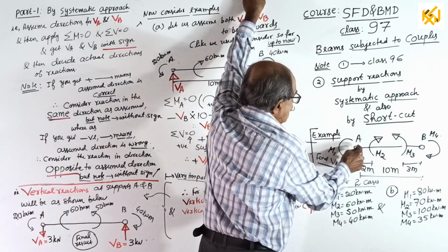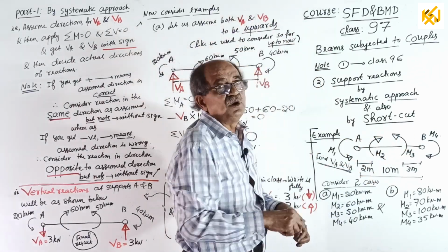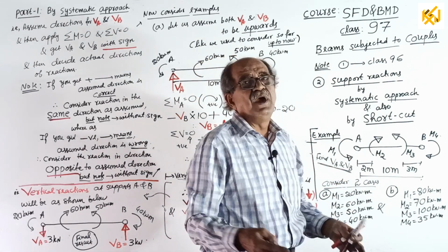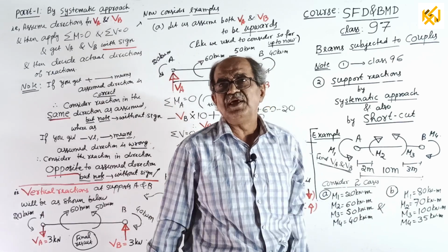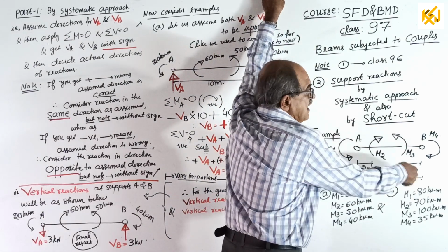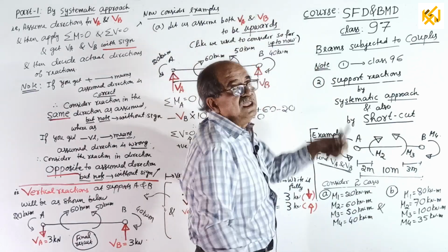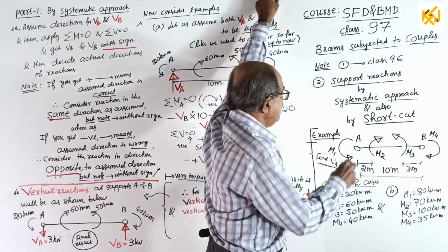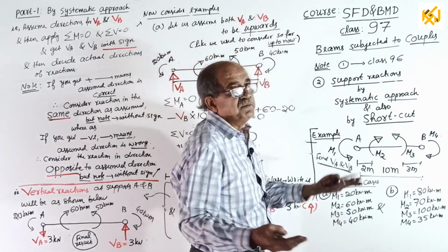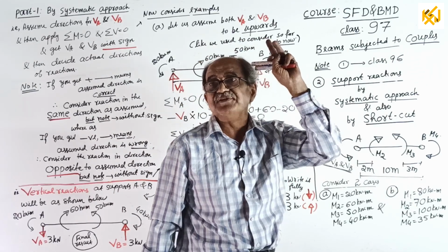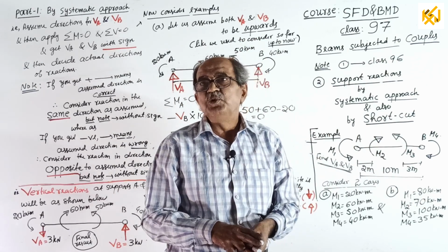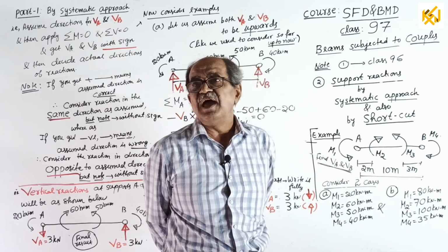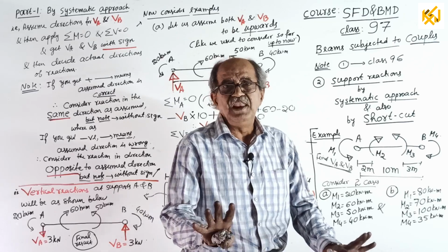So today you consider two pinned supports or hinged supports. Pin or hinge support means vertical reaction and horizontal reaction. Horizontal we are not interested in today; they are not there for SFD and BMD. Only vertical reaction. If horizontal reaction is considered for this beam, it is statically indeterminate. But if you consider only vertical reaction, it is determinate. This also I told in one of the classes. Both pinned: if you consider only vertical reaction and moment, it is determinate, but if you consider horizontal reaction, it is indeterminate. We will see later. Okay, start.